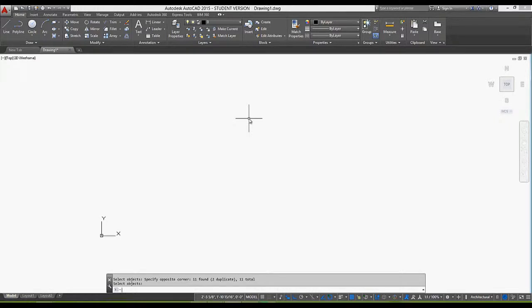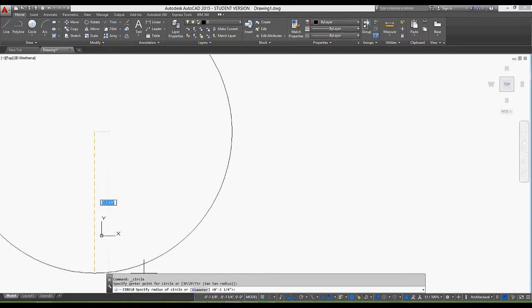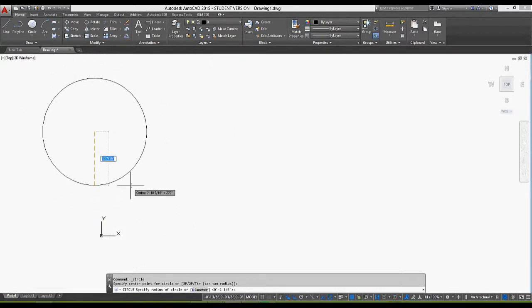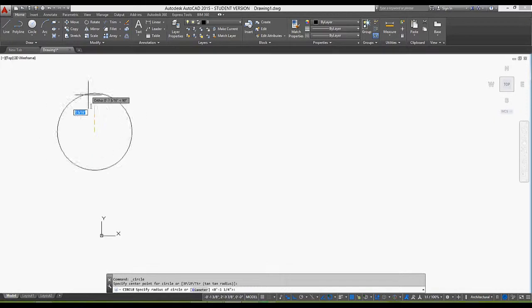Next, for the copy tool, I'm going to create a circle, like how we have made them before. Before we made it arbitrarily, but now I'm going to give it a dimension, let's say the diameter, to get a little bit more advanced. With the circle tool, it's going to ask us to specify the center point first, so I'll do that and click. Then down below it asks me to specify the radius, which is the default. So I could type in 6, and it will give me a foot diameter.